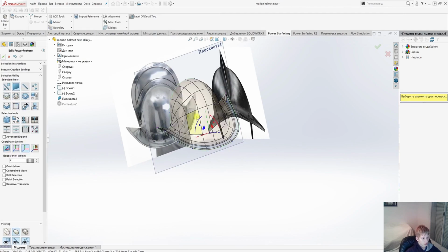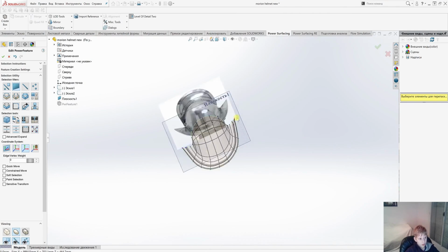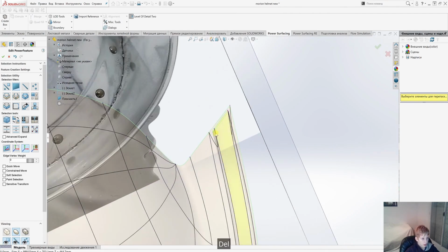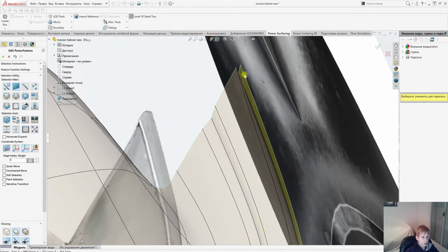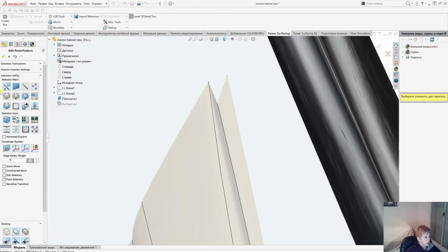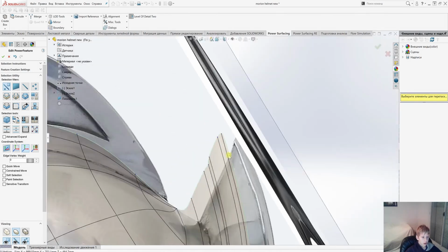You can see that there have been some minor geometry issues. Let's select them and delete them. And now let's fix these points on both sides. We'll select them by choosing Point, Edge, and Polygon. Select all our points on the edge. Right click and choose this command. Excellent! They've snapped together at this point.